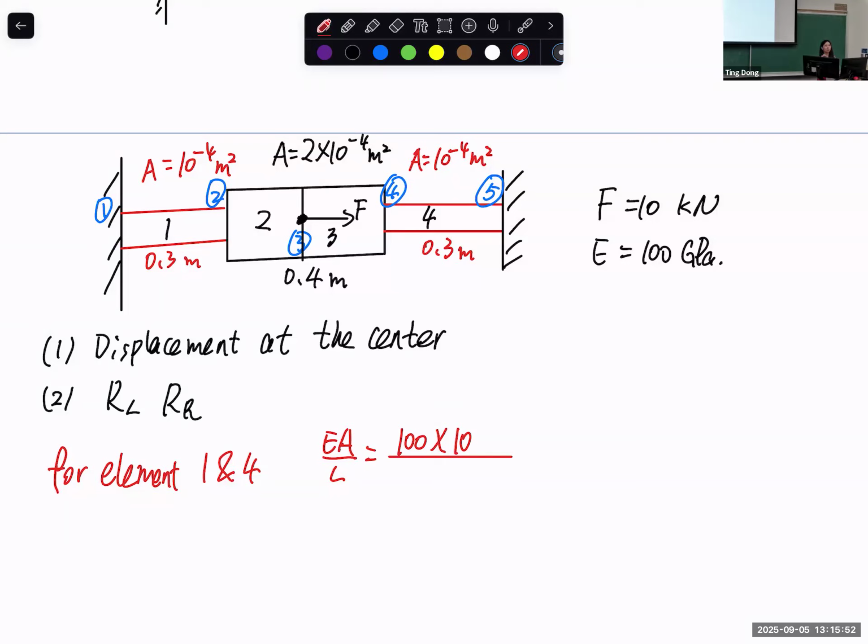You need to be careful what numbers you put in, so you know what stress unit comes out of Abaqus. So Pascal, cross-section area in meter squared, and length equal to 0.3.